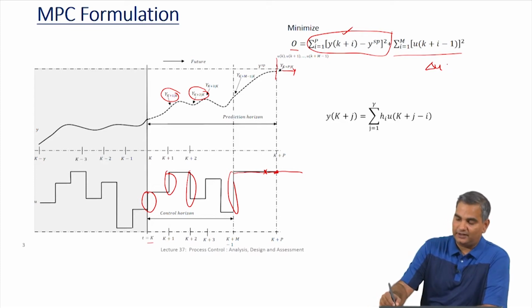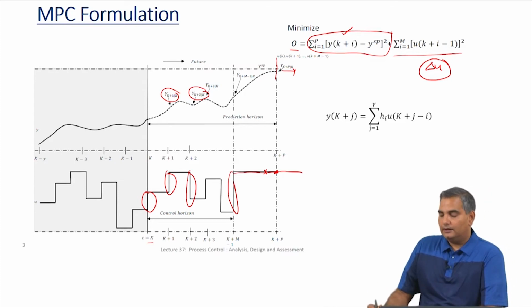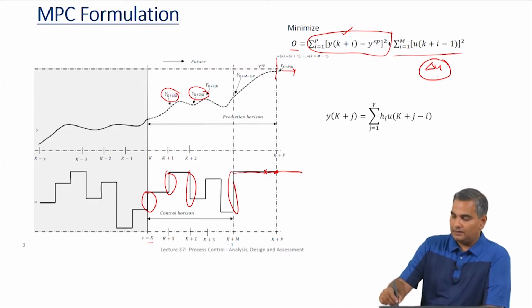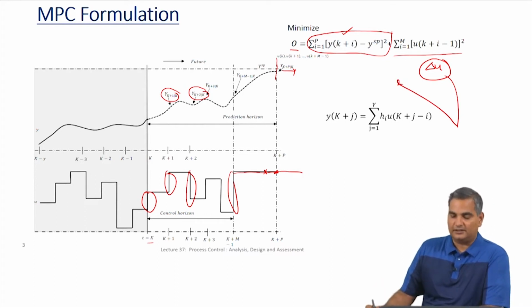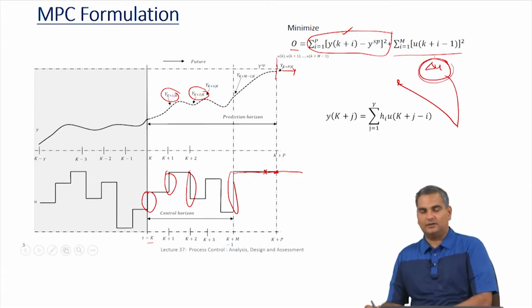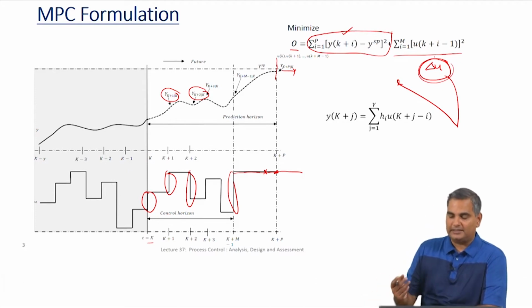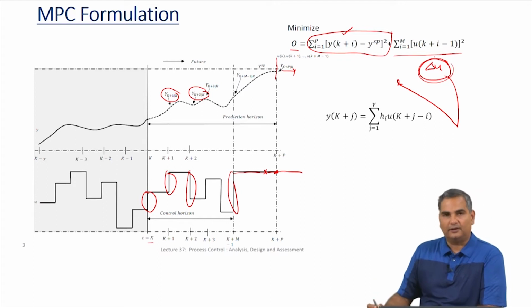So, if I want to have constraints that I want to impose on this, then I could either put them in constraints here, or I could add them in the objective function, and since I am minimizing this, all these delta u changes will also be minimized. Okay. So, there are two options, but traditionally people put that in the objective function and then weight these various objective function terms and then correspondingly tune how aggressive I want my controller to be and so on.